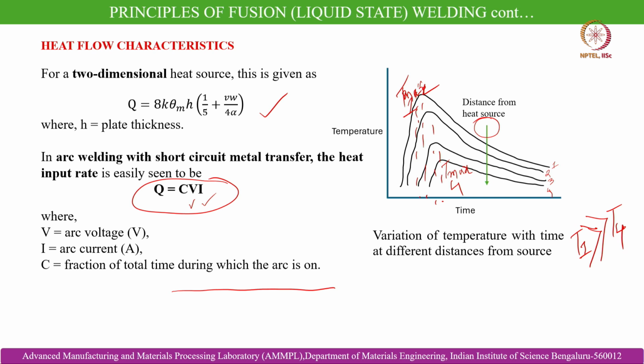That is understandable, because with time, in case of fusion welding, the melt pool experiences solidification and loses its heat content by releasing heat to the ambience, thereby going through the phase transformation process, that is liquid to solid transformation, that generally happens in the fusion welding process of metals. Because of that, the heat loss happens and the temperature drops.